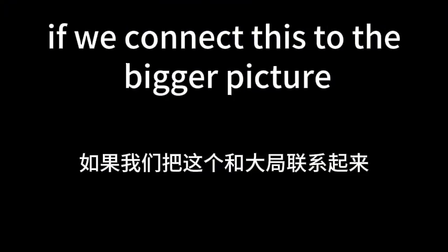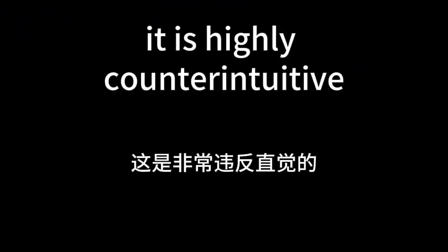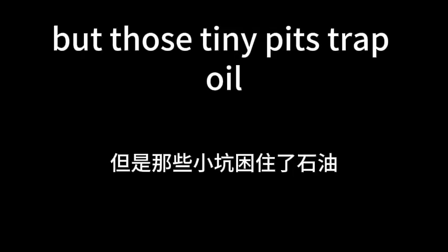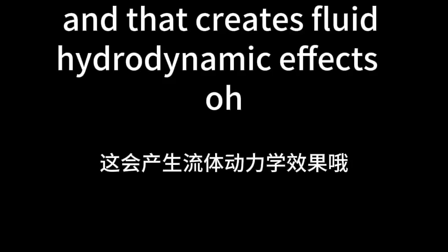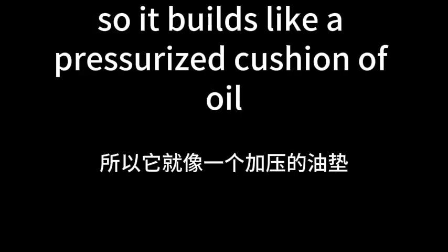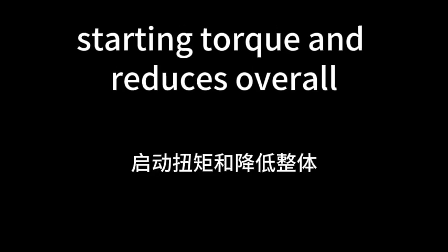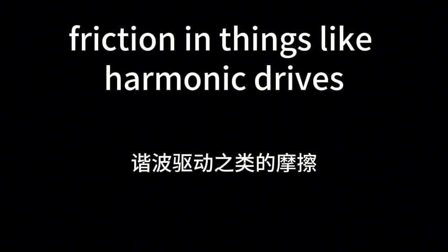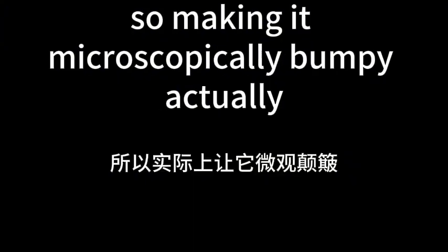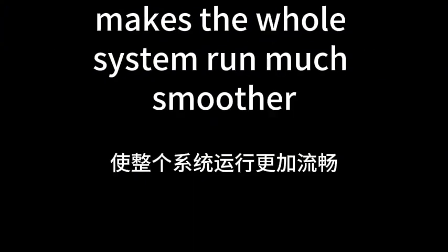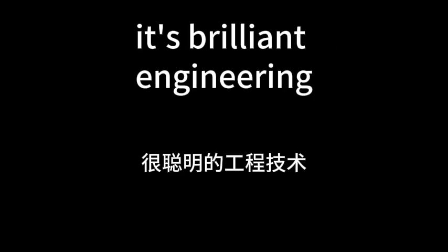If we connect this to the bigger picture, it is highly counterintuitive. But those tiny pits trap oil, and that creates fluid hydrodynamic effects. Oh, so it builds like a pressurized cushion of oil. Exactly right. That cushion dramatically lowers the starting torque and reduces overall friction in things like harmonic drives. So making it microscopically bumpy actually makes the whole system run much smoother. That is just wild. It's brilliant engineering.